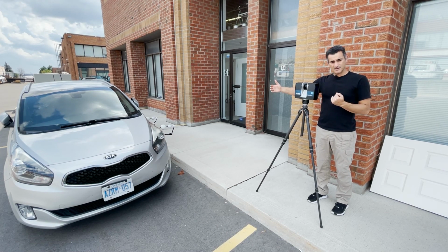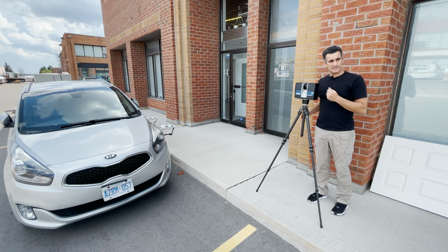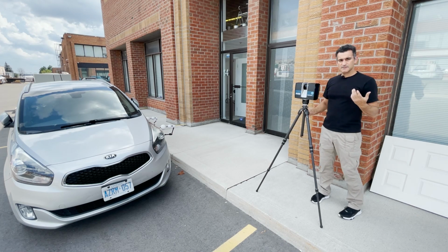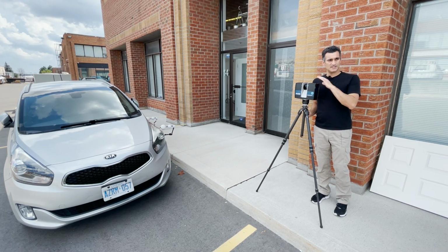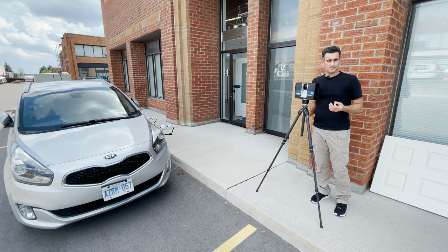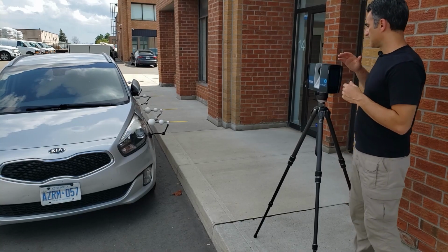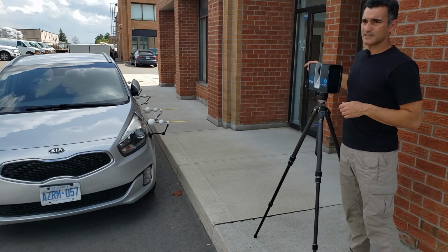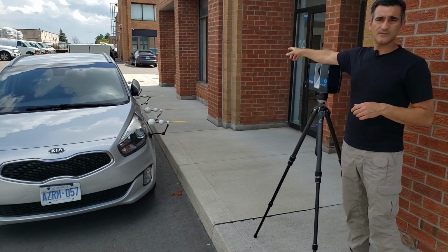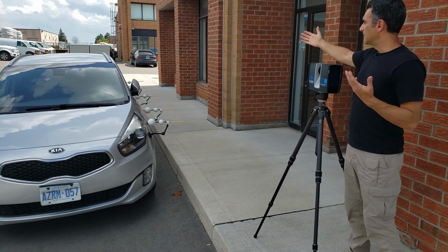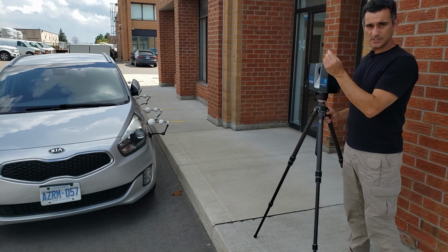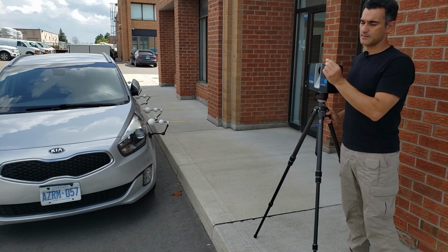And if I lower it down, I'm going to get fewer and fewer points. So the points are going to become more spaced out. So just to give you a good outdoor resolution with this particular scanner, it's also very common with other scanners too. It's 1/4 resolution, so it's basically just over 6 millimeters point spacing at 10 meters. So if you think about here, about 10 meters away, and I'm not sure if you can see there's like a mailbox down there, but basically, around that distance, the spacing between the points that this thing's going to pick up is going to be about 6 millimeters.